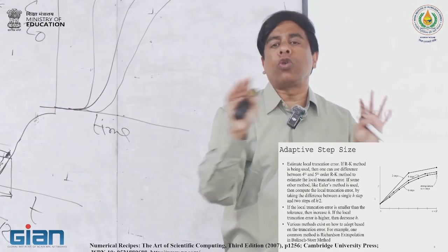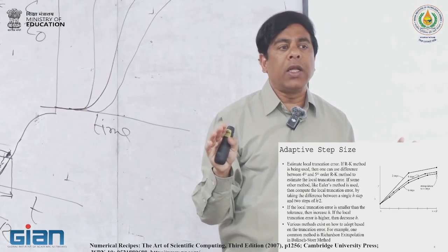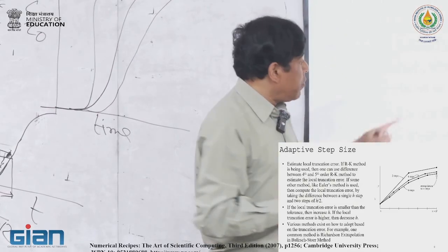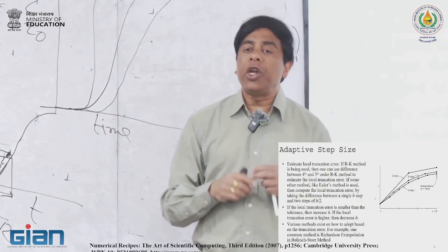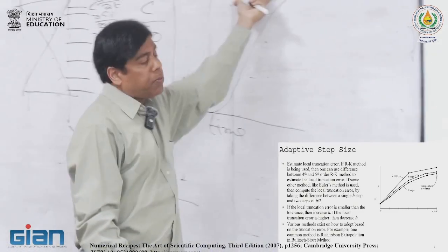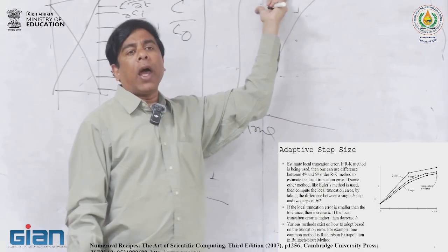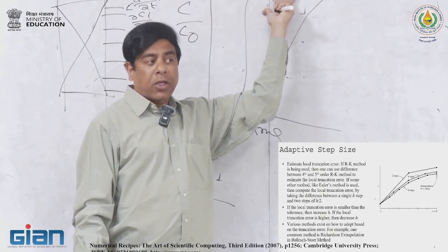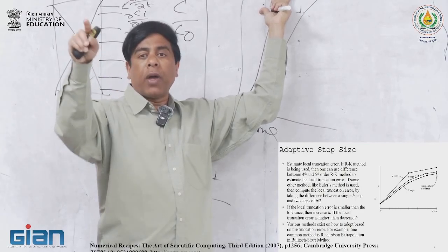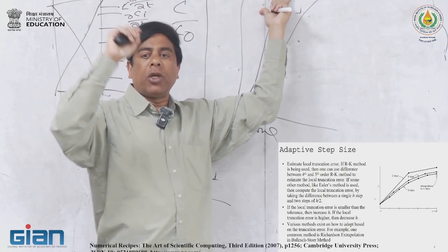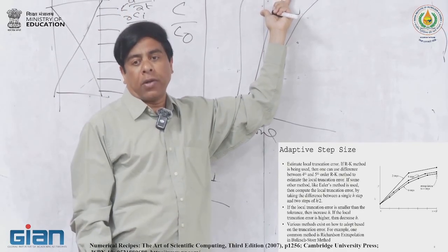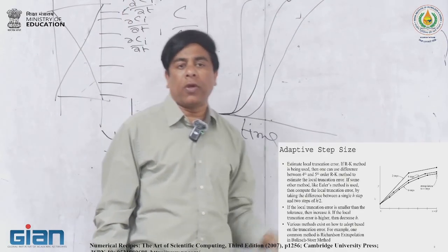So if it cannot solve at 1 minute, it will basically say, sorry, convergence failure. On the other hand, if you satisfy the local truncation error and you increase the step size, which you want to do here, then at some point it has to stop. Whatever upper limit you provided, like 5 minutes or 6 minutes or 10 minutes, it will not let it go beyond that. So this is how this thing is done.